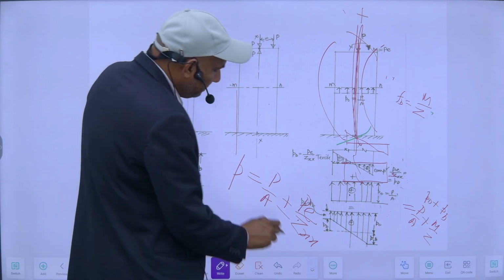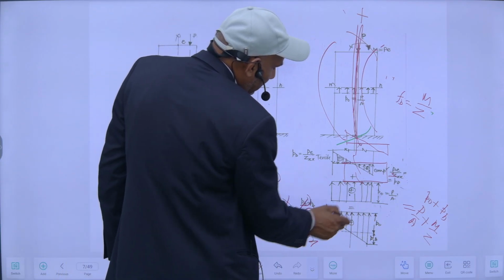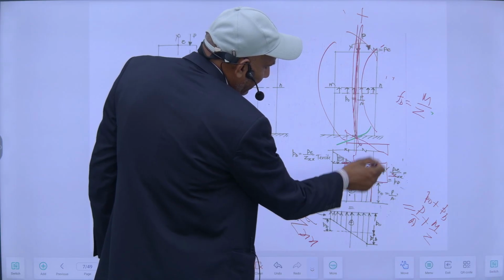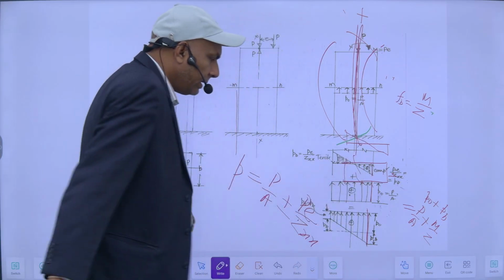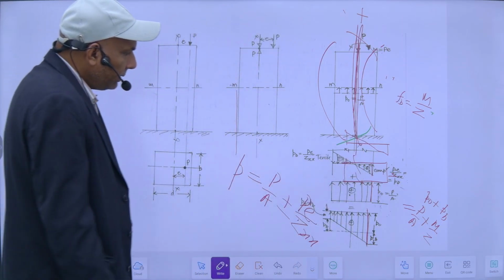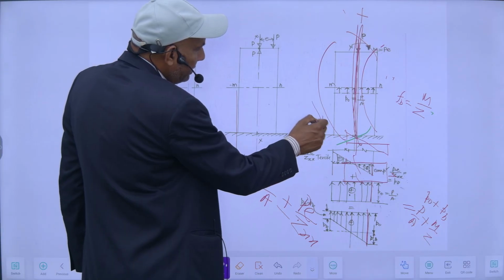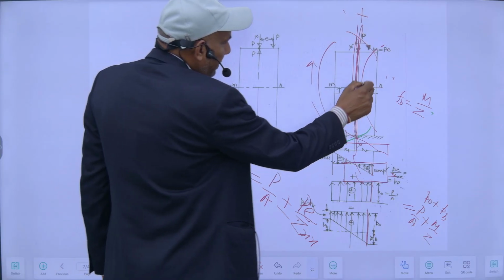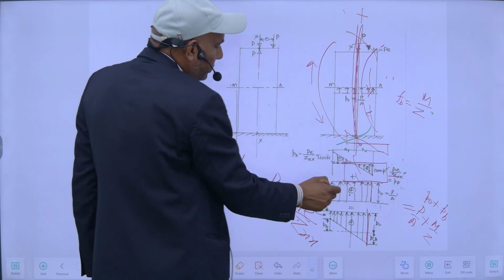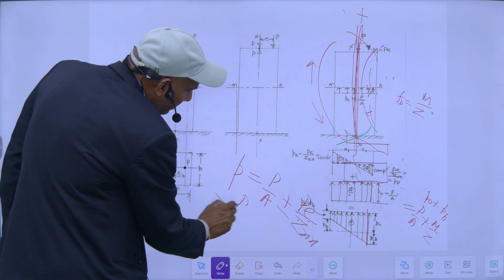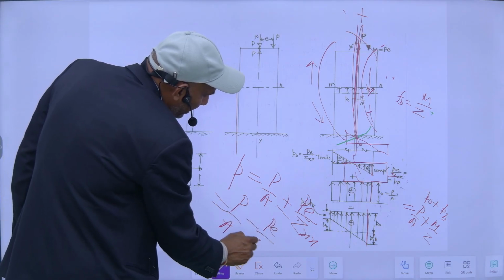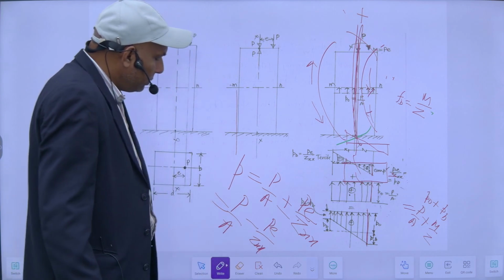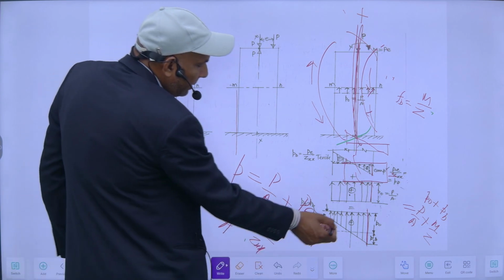So this will give the final resultant stress. Since the direct stress is compressive, and the bending is also compressive here, both are compressive, so it will be like this. And on this end there is tensile stress, so it is compressive here, but due to tensile bending it will be direct stress minus this M upon Z. So my compressive stress amount will be decreased.